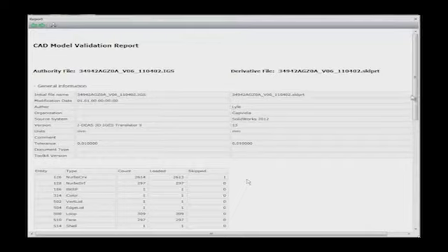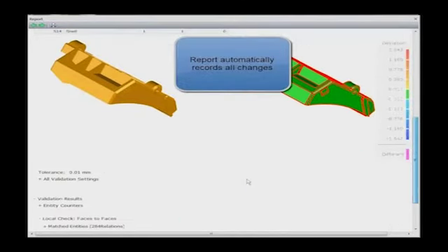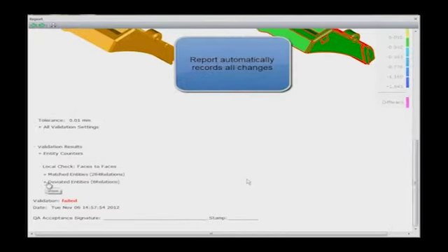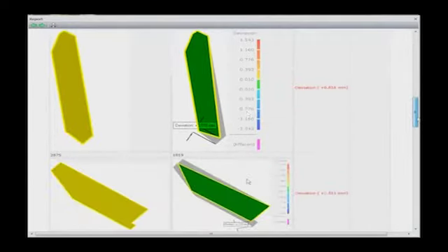We expand the deviant entities folder. We capture and hold all this information for you. So what you're seeing here, the yellow is the original geometry from the IGES file. Green is a SolidWorks surface. Gray, that's this green-yellow surface overlaid to show you where it actually should be. So you can clearly see here pieces of the corner, piece of that edge was collapsed, and what it was supposed to look like.